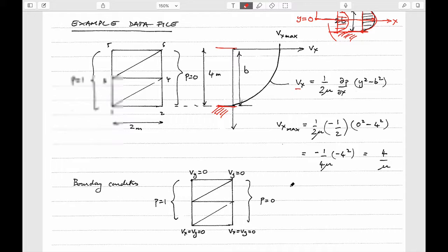If we want to solve for it, then we want to put some finite elements in there. So I'm going to put these elements that make up this geometry here. And because we know how to do it, we'll use triangle elements. And then what else do we need to do? I guess we need to think about what the boundary conditions would be. And so what would the boundary conditions be that we put on here?